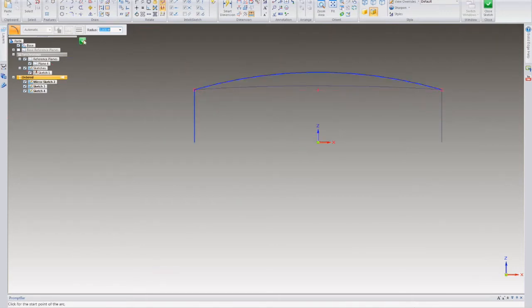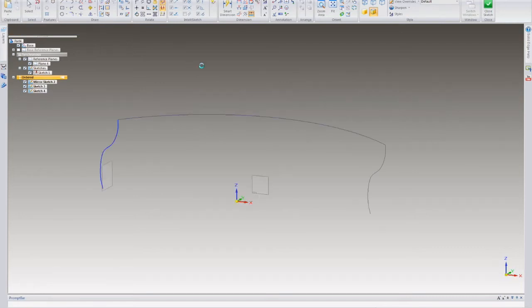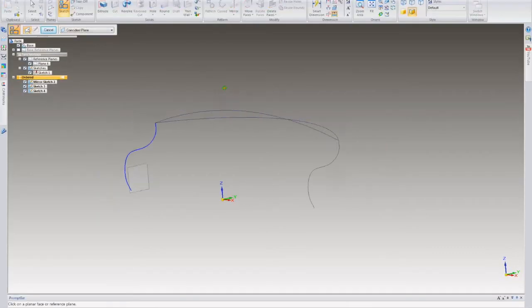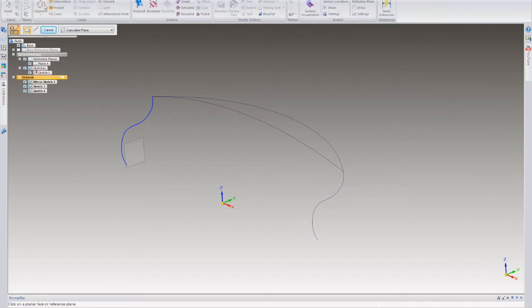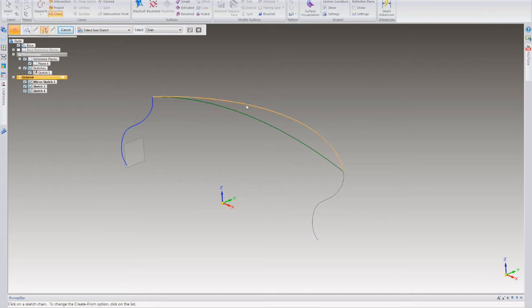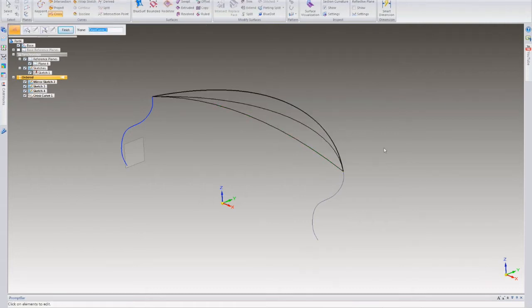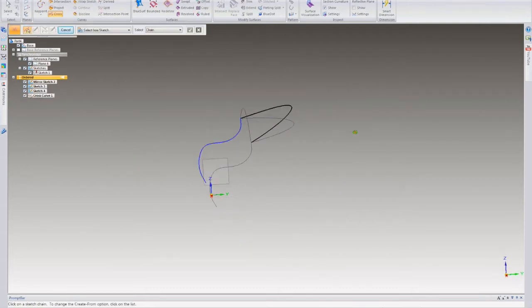And let's give it a little shape. That'll work. I'll just leave that one free so we can rotate it. All right, so now I have two sketches here. So basically, to create a cross curve in space is basically grabbing both of those geometries and telling it where they're going to meet. All right, so I'm going to say, you know what? I want to see where this guy and this other sketch would meet in space. So there's my third control point. So now I get a 3D curve.